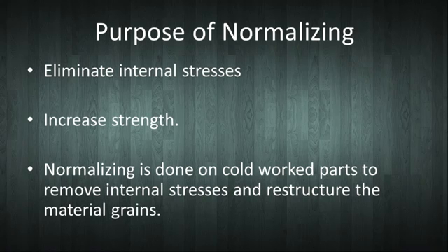Purpose of normalizing. It is used to eliminate internal stresses. It is also used to increase strength. Normalizing is done at higher temperature than annealing, and the ductility obtained in normalizing is somewhat lower.